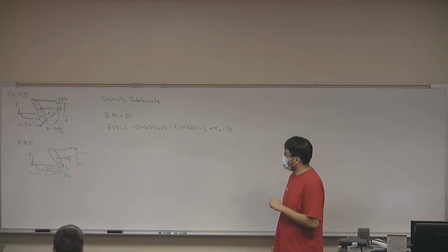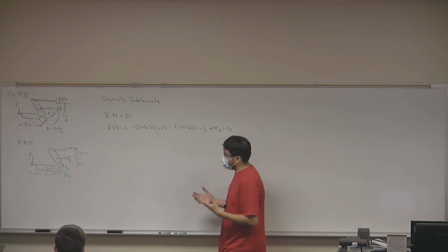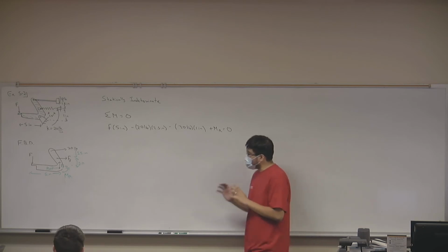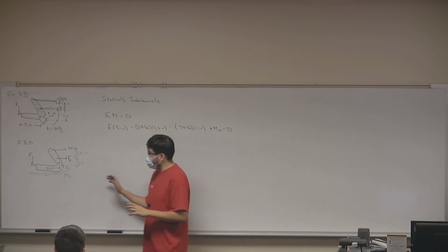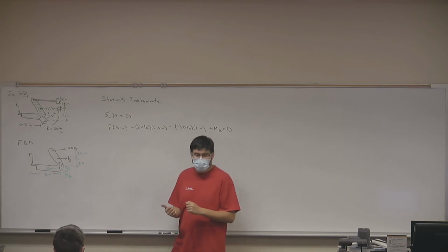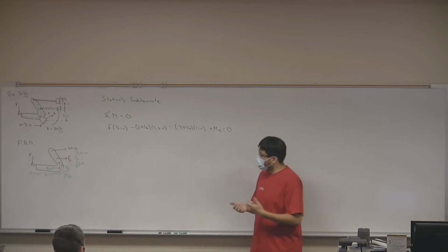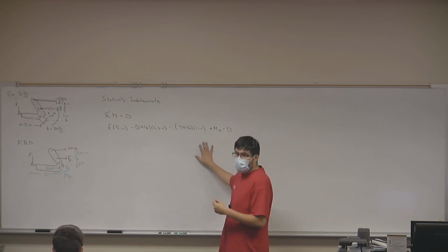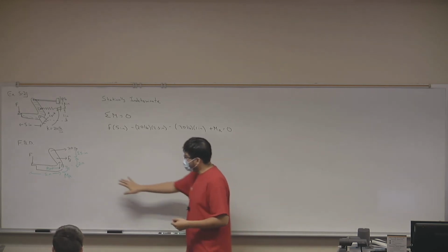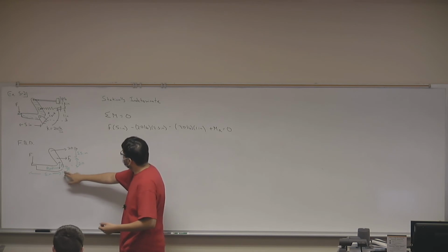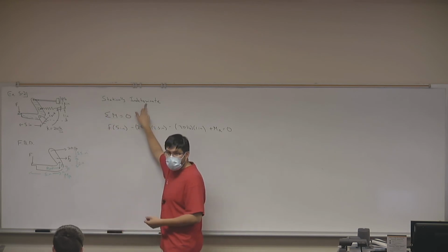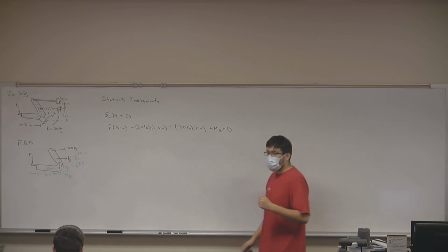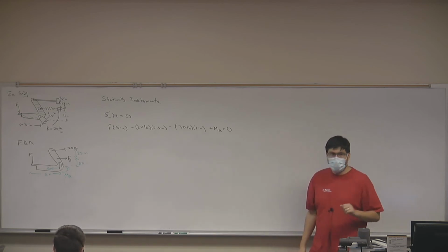Okay? So from a design standpoint, you need to be careful, because some systems may have more supports than needed to keep it balanced, and more supports than needed means more unknowns than equations, which means that we cannot solve it. A system such as this, where it has a fixed support, is a statically indeterminate system because we cannot find all the forces and reactions in the system using statics equations.